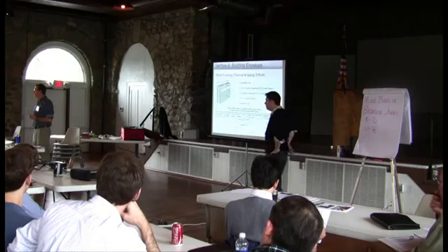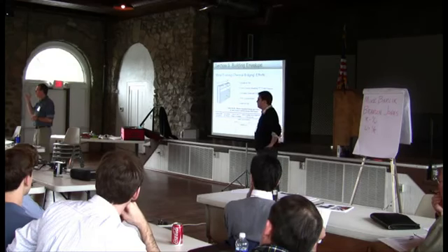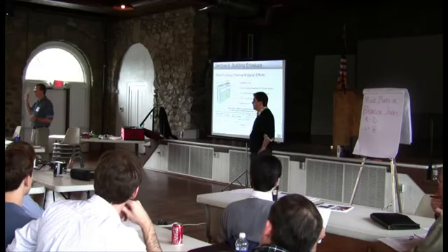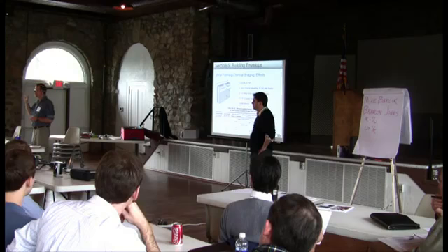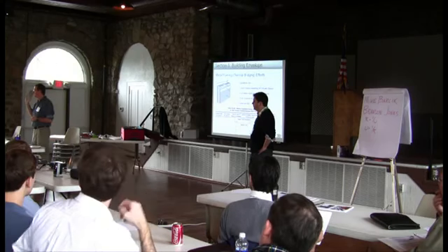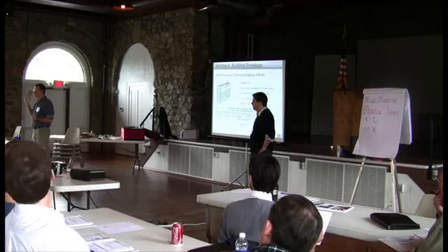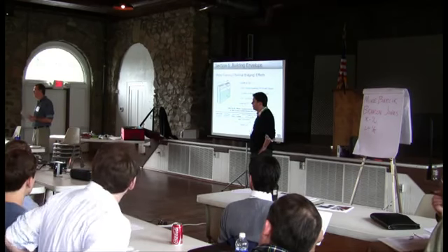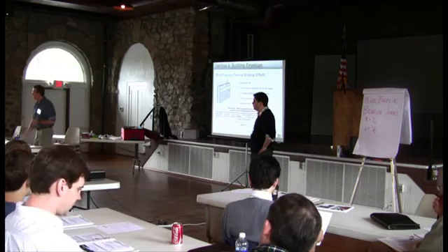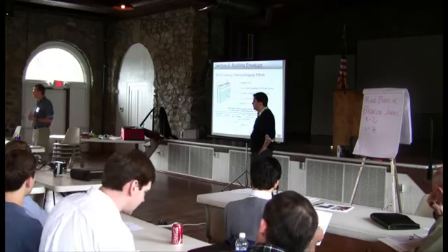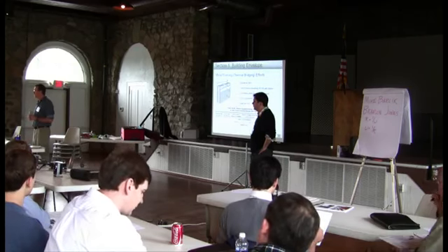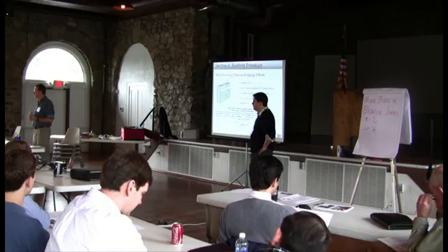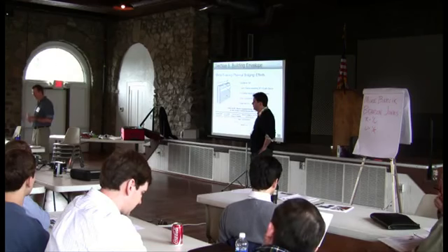Well, the only problem is, does anybody know what the R value of gyp board is? How thick is the gyp board on the outside? Depends on whether it has to be rated or not. It's normally half inch. Yeah, it's about a half an R value. Okay, it's not good, is the problem. Should I replace the gyp board with maybe, well, no, because you just have to bite the bullet. I mean, if you have to have a rated wall, it's got to be 5/8.